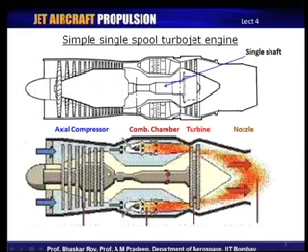So, in this particular basic engine, we have a single shaft, and this single shaft runs the entire compressor that is shown over here. And as we see here, it has a series of compressors, really speaking. We will be talking about this series of compressors as we go along more and more. So, this turbine runs this entire compressor, and having done its job, releases the high energy gas. It still has very high energy, very high pressure and very high temperature.